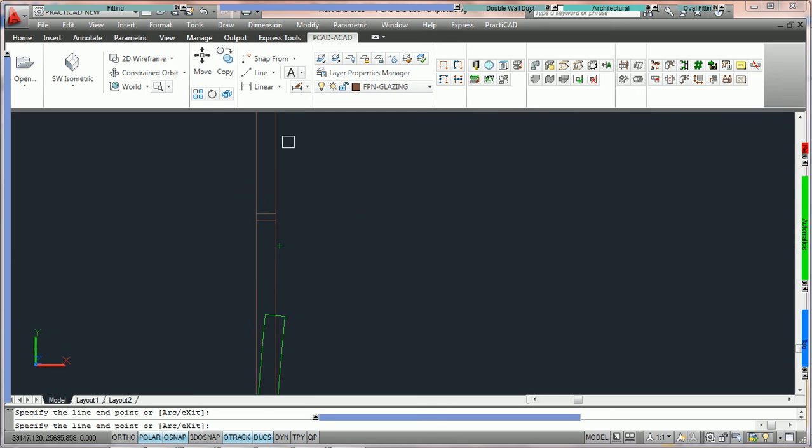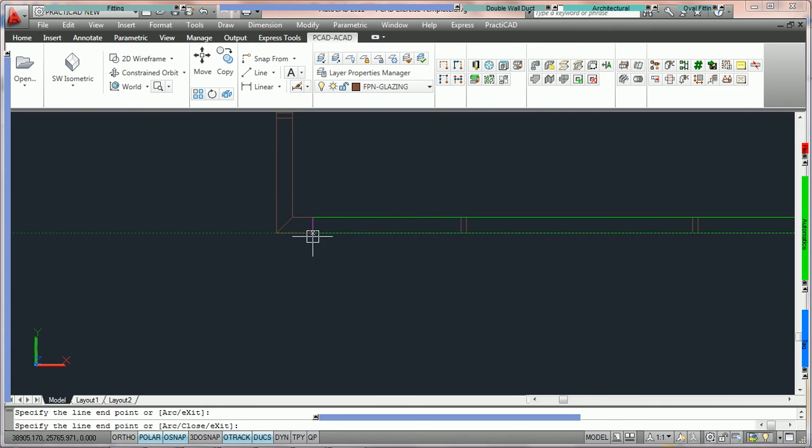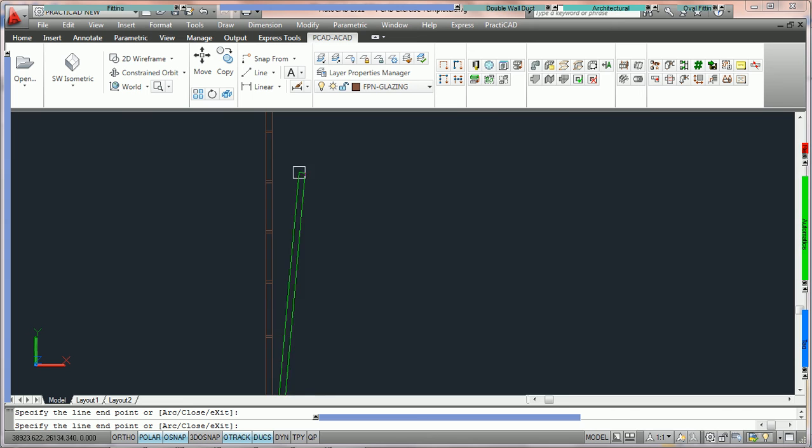Then we're going to turn up, and we're going to go through this break, and we're just going to hit. Notice that right here we're going to stop at this corner point. We're not going to go here. Because we're holding it by the bottom left, we actually want to stop here. We click, and when we turn the corner, PractiCAD fills that with a wall for us. So we're just going to complete here. We're going to go up, and this should get you comfortable with actually tracing walls in the system. So in this exercise, we're just going to stop once again.